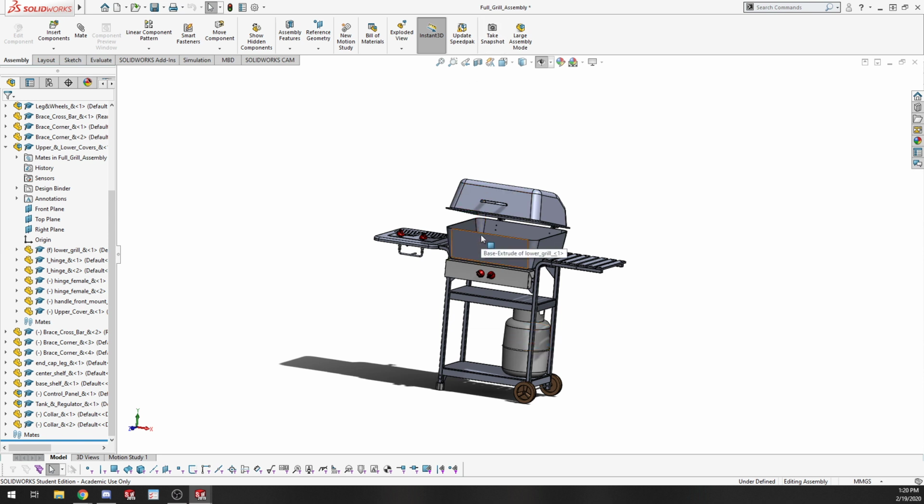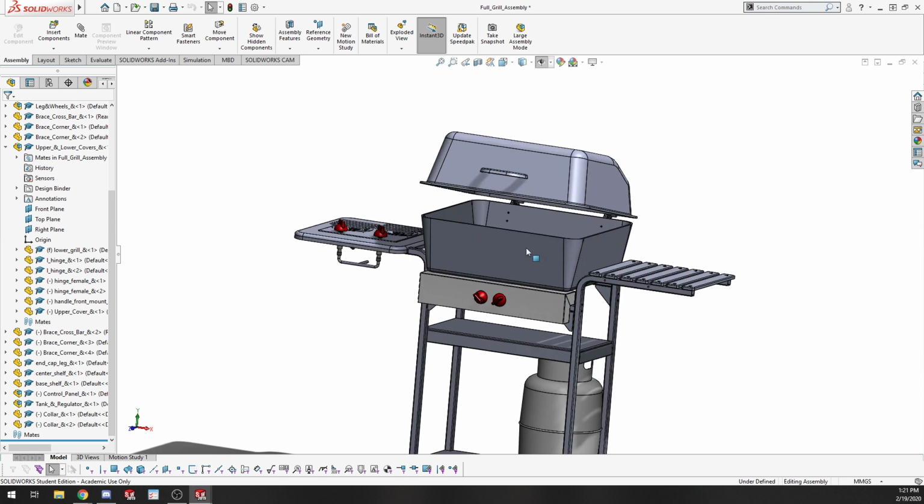Sometimes when you define things in a particular orientation within your sub-assembly, you make a configuration, you want it to stay like that. You're just positioning it kind of open within your sub-assembly, you plop it into a full assembly. It doesn't, basically SolidWorks doesn't fully transfer everything into the big assembly file in order to keep performance up. So the bigger your assembly, if it's trying to resolve all of those mates all at the same time, it kind of just saves it as, basically treats it as a part now. It doesn't go through and try and recalculate all of those mates.